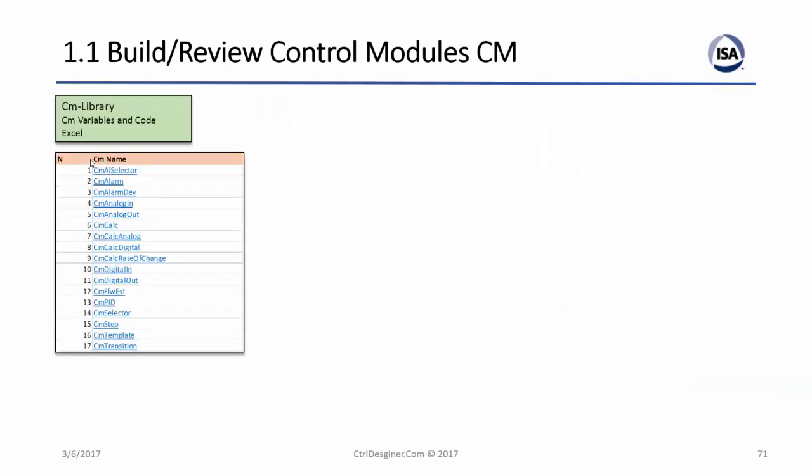That means that whatever project you do, you need to have a basic set of building blocks. We call them CMs. And if you remember, these CMs are basically the building blocks of process control applications. And as we discussed before, they should have enable logic, disable logic, parameters, code, and visualization. Therefore, we assume we have this, or you have developed a library from the vendor, so that we have this list.